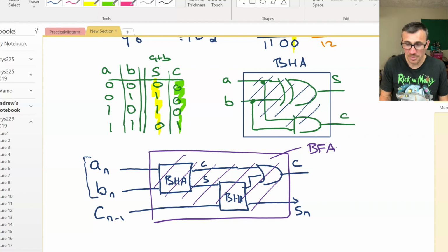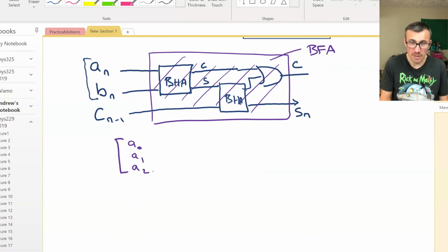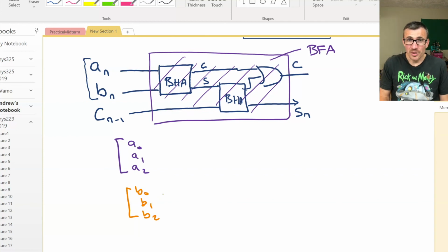How are we going to wire that up? It'll be something like this. So we'll have our first 3-bit number, 0 through 7. For example, 5 would be A0 equals 1, A1 equals 0, A2 equals 1. But let's just leave it abstract for now. So we have our second 3-bit number, B0, B1, B2. Again, these can be either 0 or 1, and we can make any 3-bit number this way. And let's wire them into our adder circuits.